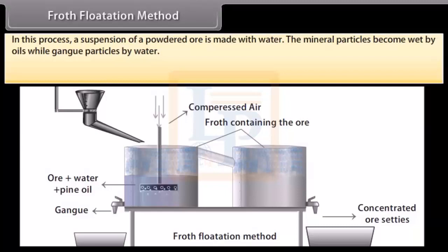Collectors like pine oil, fatty acids and xanthates are added to it. Froth stabilizers like cresols and aniline stabilize the froth. The mineral particles become wet by oils while gangue particles become wet by water.